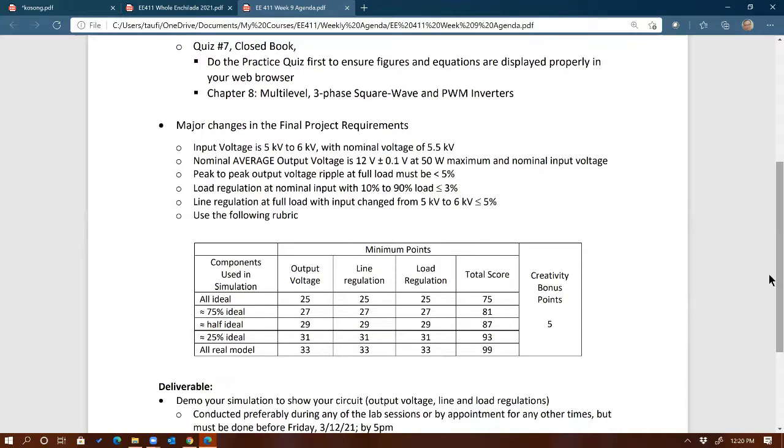And then at the point of the load, right? So at the sensors themselves, they are not high voltage, right? They're operating at low voltage, so most likely 12 volts. So that's why you have to convert from this high voltage to 12 volts, right? And they're running multiple sensors. So usually one power supply will be able to provide power for multiple sensors at a single node.